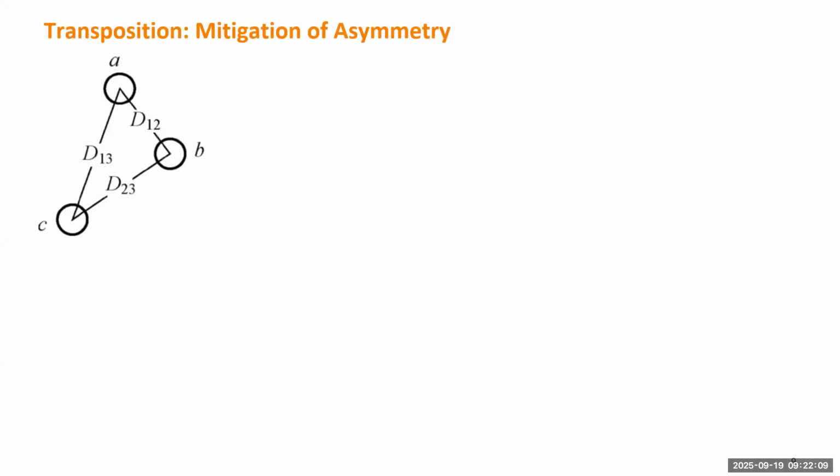So in reality, if you look at the 3-phase transmission lines on the high voltage tower, usually the line is not laid out at like a perfect triangle of 60 degrees, right? So usually one distance can be longer and one distance can be smaller. So how do we deal with such an asymmetry? One idea is called transposition.